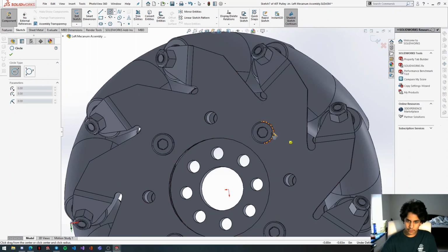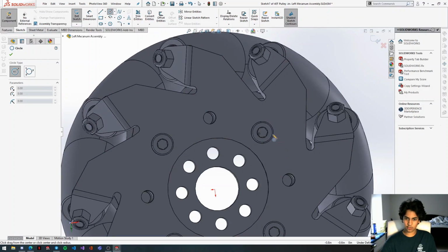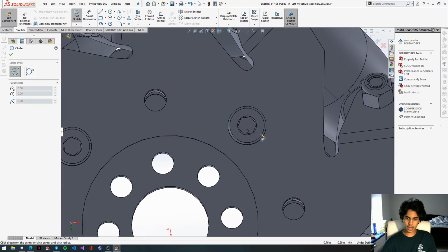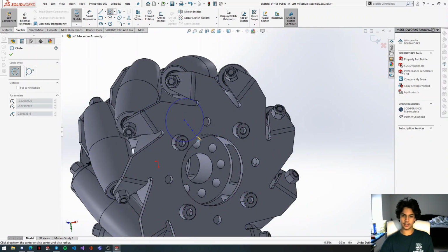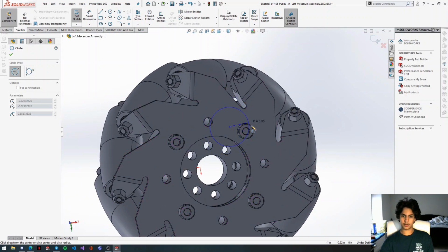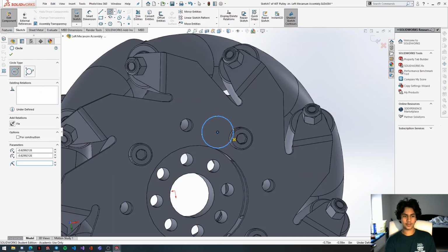When we hover over the screw, as you can see, it turns orange, and then we have a little crosshair right here. You're going to align your pencil with the crosshair, and you can see a little coincident icon next to your pencil, that yellow icon right there. You're going to create a circle there. It's lagging a bit, and you can see that it's automatically aligned perfectly to that lock nut. Now we're going to type in 4.5 millimeters.